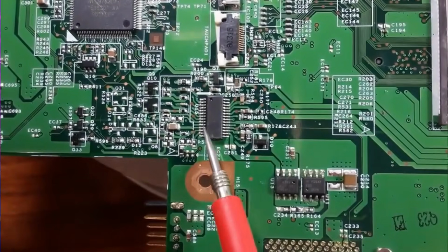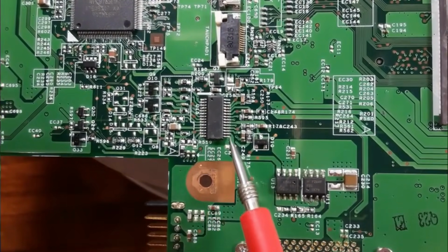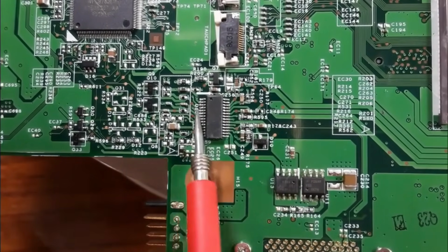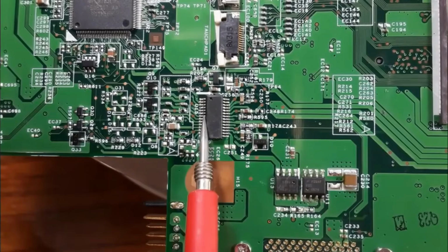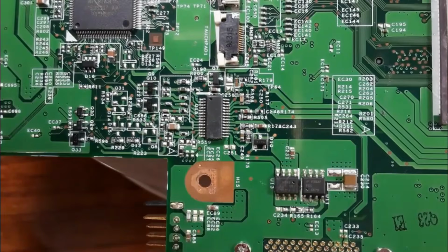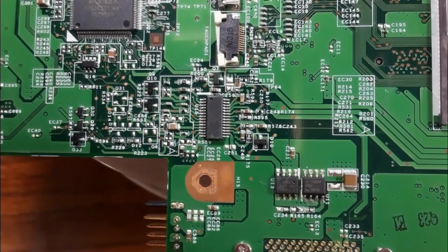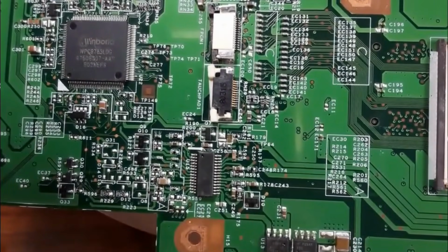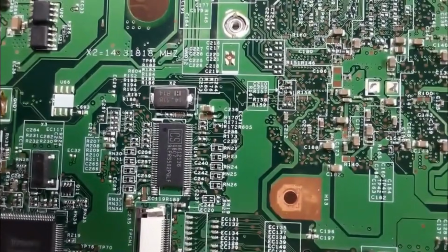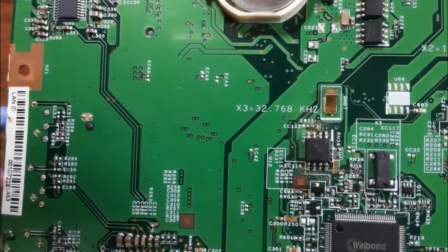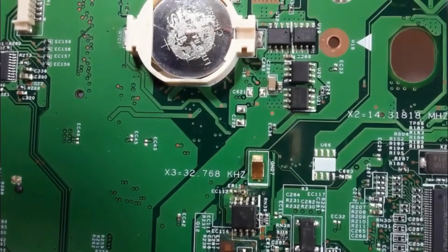Okay, as you can see here, for this IC we have these buses. Each pin is connected to a component here. If we check the continuity between this pin, for example, we will find this pin and this capacitor are connected together. Okay, so if you understand how to use these buses, you can troubleshoot any motherboard without its schematic. Okay, I will show you in the next lectures how to use these paths and buses to troubleshoot the motherboard and to track the signal.